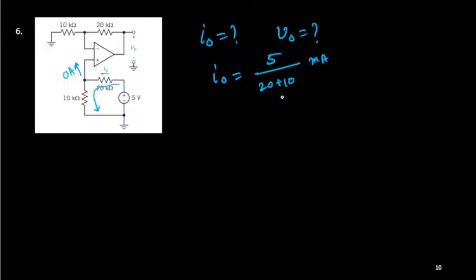Is it fine? So this is 5, and this potential we can find out, but the thing is that this supply voltage will provide a certain current I naught, and the same current will flow to this side. So I can consider 20 and 10k in series. So 5 upon 30 means 1 upon 6 milliampere.